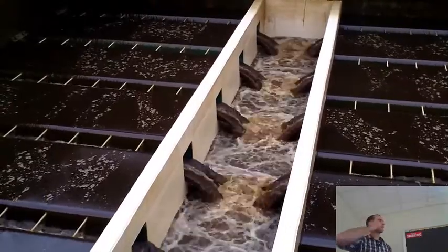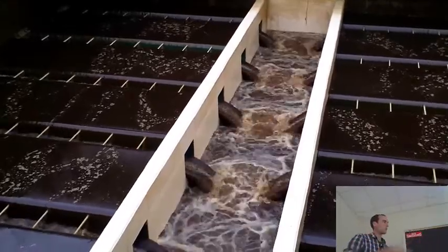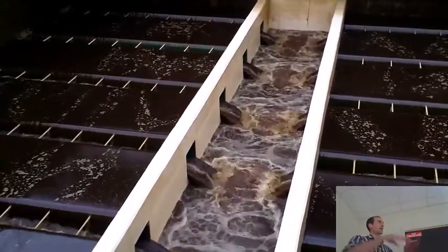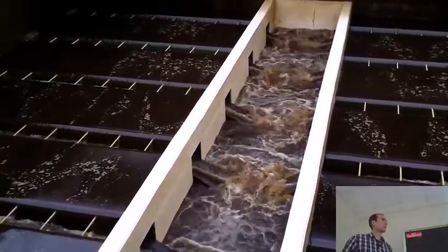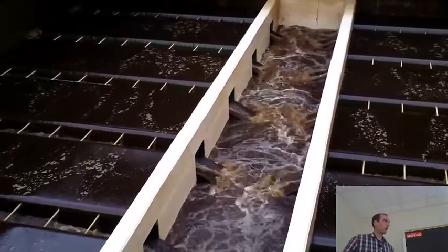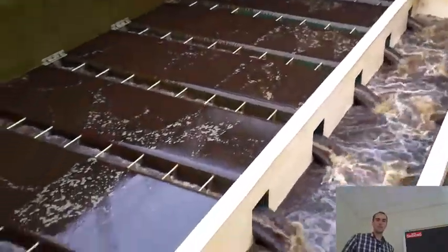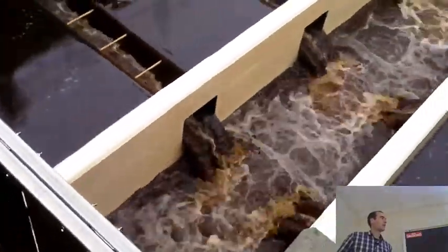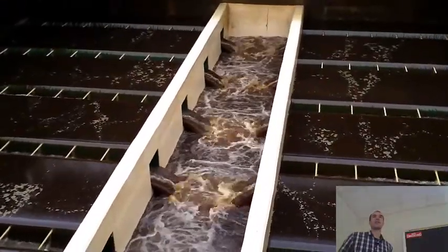And it's pretty typical to see these with these trough systems. When you're loading water to be treated, you'd use this central trough and flow into it, and then it would disperse into these troughs and go onto the beds from there, and then for the backwash, the whole process kind of reverses, draining water out of that centerpiece, as you see. So you can see why we're going to send that water to a wastewater stream, and it's so full of particles that it's probably going to be pretty easy to do some flocculation and sedimentation on that as the first steps.